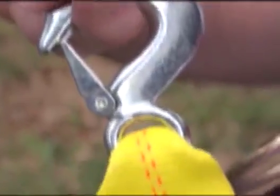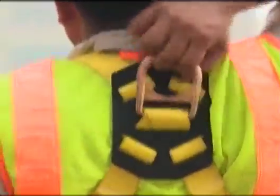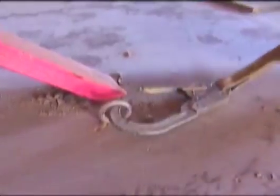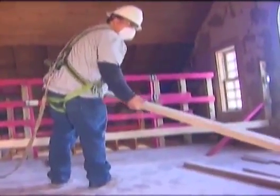Lanyards can range from 18 inches to 6 feet. Deceleration distance should be 3.5 feet, the maximum allowed by OSHA. HW is the distance from the D-ring located on the upper back on the body harness to the working level, generally about 4 to 5 feet. A safety factor of at least 2 feet should be used, but 3 feet is suggested.